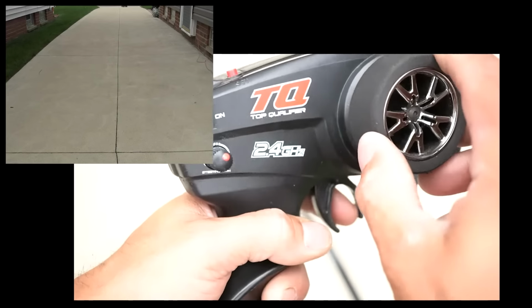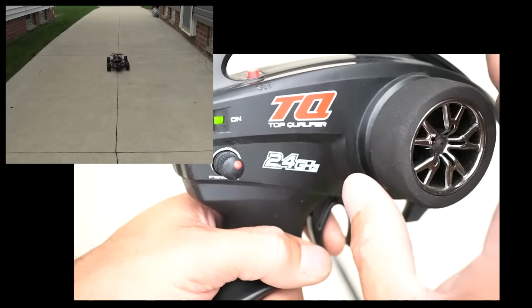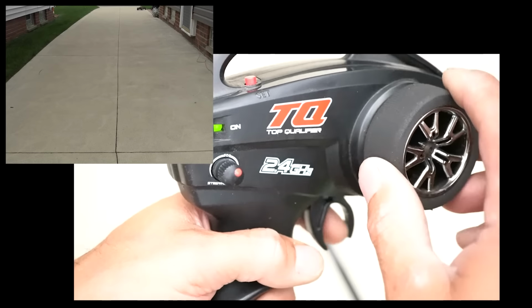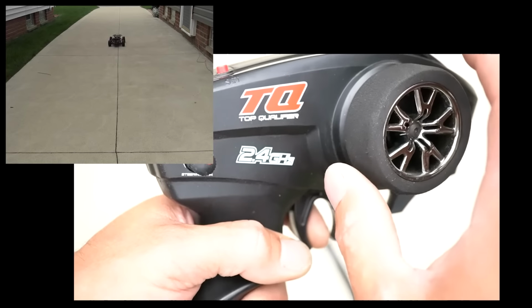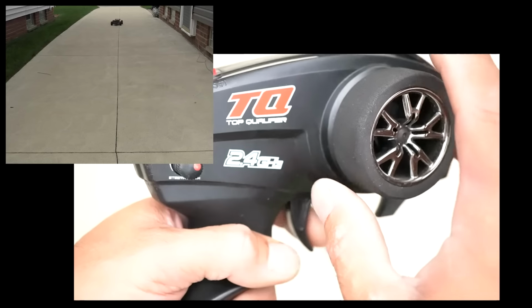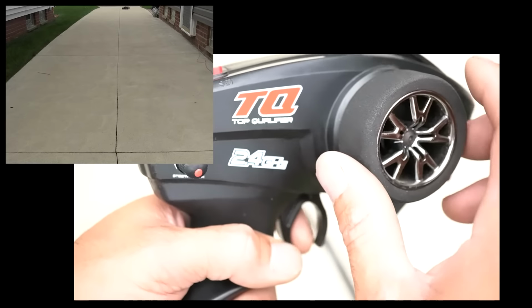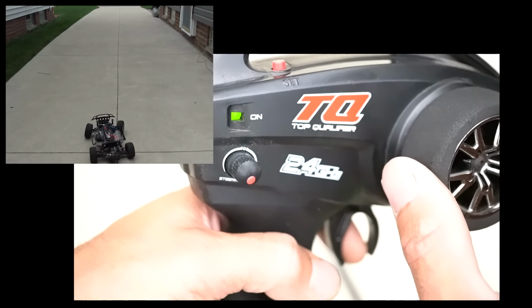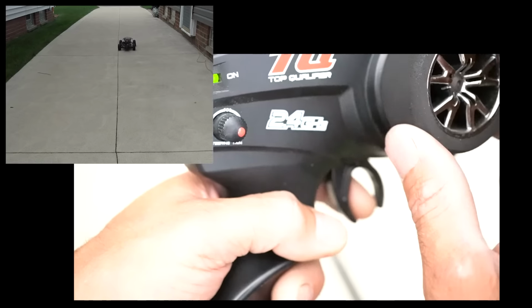So I make a minor correction. So I need to make a minor correction to my long term, and now I have to make less of an adjustment to my short term. The goal of the engine computer is to have the short term close to zero. So we're going to keep on going here, and sooner or later, I'm going to overcorrect. Look, if I turn my trim all the way to the right, now we've overcorrected, so we got to back off our long term just a little bit.